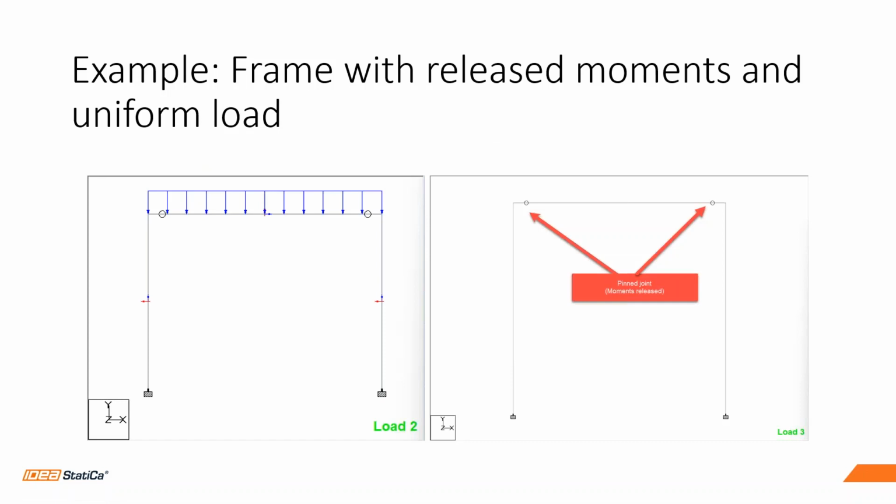I modeled this frame in a structural software where you can analyze 2D or 3D structures. I did a simple frame with this beam over here, released the moments for that beam, and input a uniform load to this element.